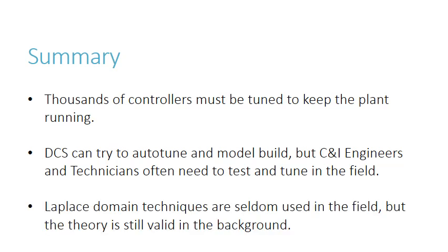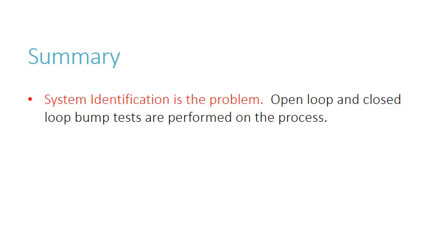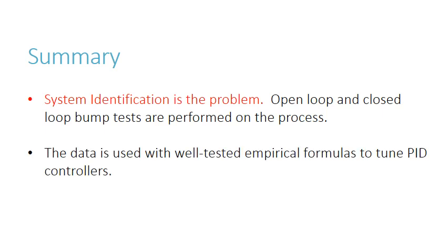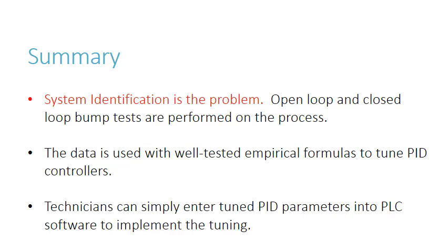Laplace domain techniques, as far as I've seen, are not really used in heavy industry that often. System identification, model identification is a big issue. When you want to use those techniques, you need to have a good model. The best models come from data from open and closed loop testing that's been done for many years now, and that's a science in and of itself. The data is used along with well-tested empirical formulas, which can be used by technicians, or even by more sophisticated Laplace domain techniques, and then you can tune your PID or other controllers with it.